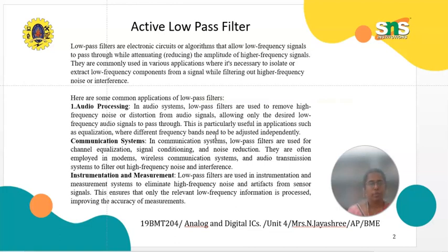They are often employed in modems, wireless communication systems, and audio transmission systems, filtering out high frequency noise and interference. Low pass filters are used in instrumentation and measurement systems to eliminate the high frequency noise and artifacts from sensor measurements. It will eliminate the high frequency noise. This ensures that only the relevant low frequency information is processed and improves the accuracy of measurements.